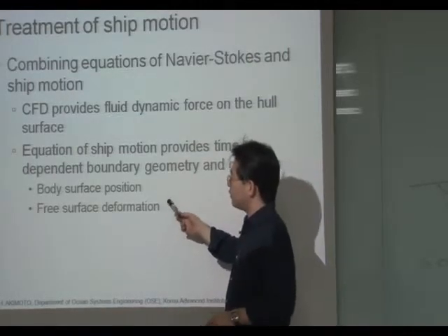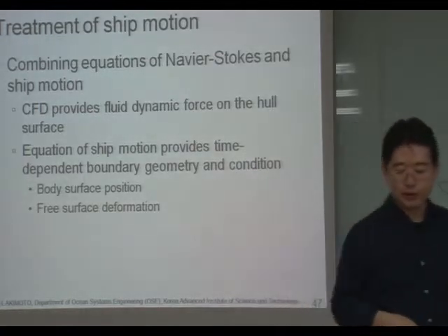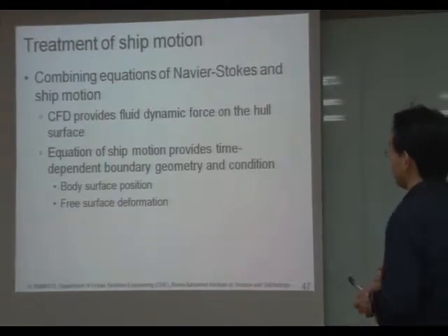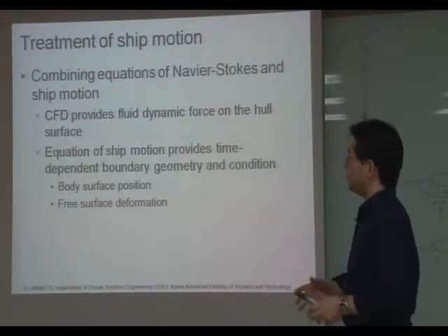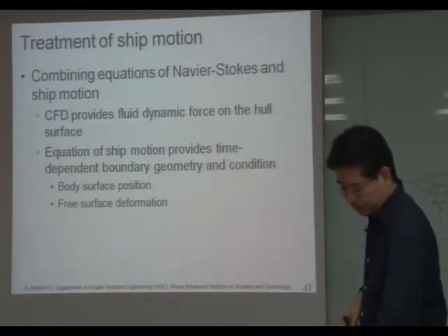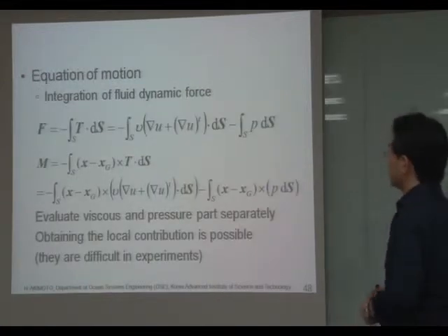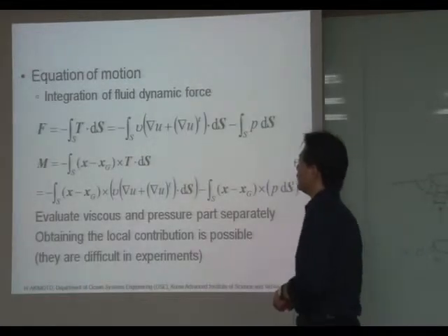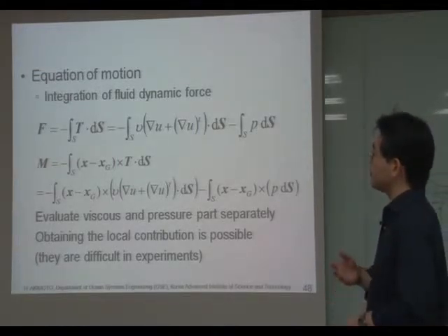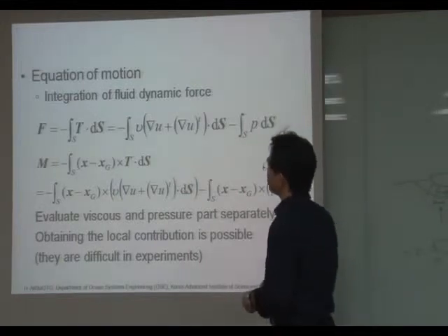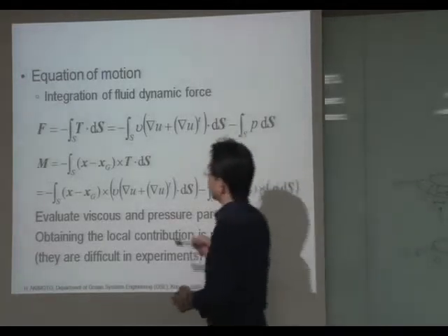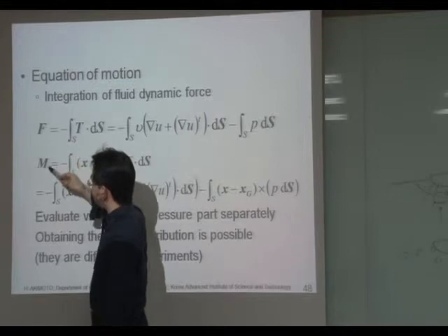So if it is unsteady motion, the free surface is also unsteady. We have to consider the interaction between the motion of the body and fluid simulation. How to get the fluid dynamic force from the simulation is written like this. We have to consider the lateral force and moment.